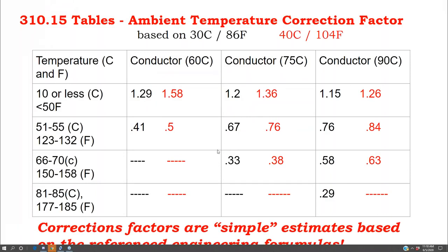So actually, if you have a whole bunch of solar circuits that are oversized because of voltage drop, and then you start bundling them together, that starts to get into, okay, well, am I bundling it to go across a walkway, or is it going to be a short section? Is it a bundle that might be 1 or 2 feet, or is it a bundle that is 10 feet long or more? You have to start applying these derating considerations. Actually, 3 feet or so.